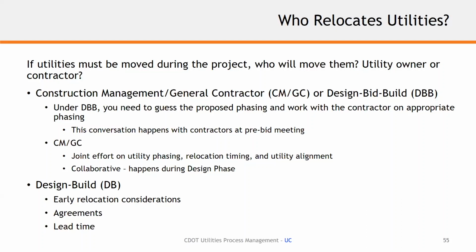specs, and then have the contractor come in and build the first 5 miles during the first season, and during that first season have the second 5 miles of utilities moved, because we knew it was a 2 construction season project anyway, that we could kind of leapfrog the utility relocations and provide 5 miles and 5 miles at a time for the contractor to do the work.